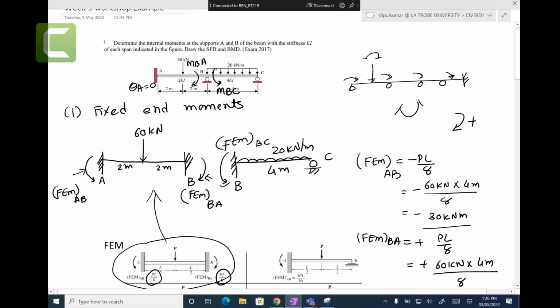Like last week, capital D. Last week we did static degree of indeterminacy, which is the number of unknown forces minus the equilibrium equations. How many forces are unknown? 3, 4 and 5. 5 take away 3, 2. That is the static degree of indeterminacy, in the force method.